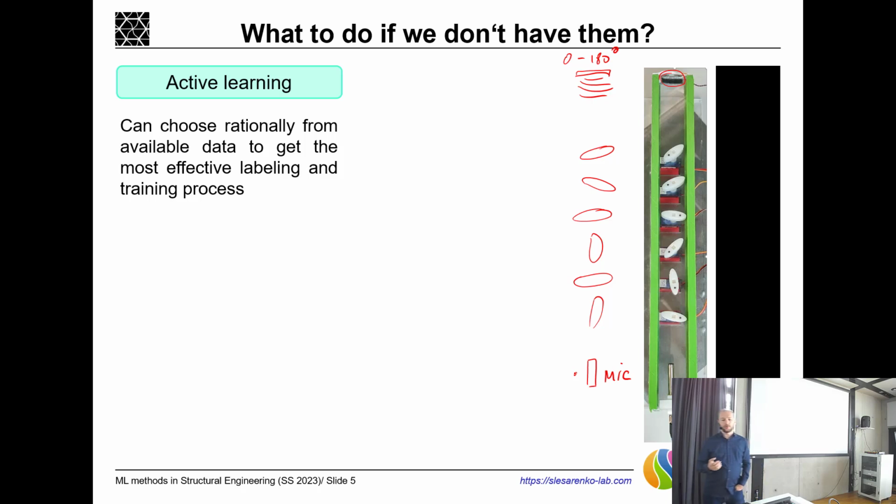Might be not so loud in comparison with what we generate. So if we have an empty waveguide, we generate 5 kilohertz with an amplitude of, let's say, 1 decibel or whatever. It's actually not exactly correct. So with some specific amplitude, and we measure what's happening, we see the same amplitude. But if we have some structure inside, our sound waves start to interact with the structure, and therefore we can measure the attenuation due to the structure interaction. And that's what we are doing.